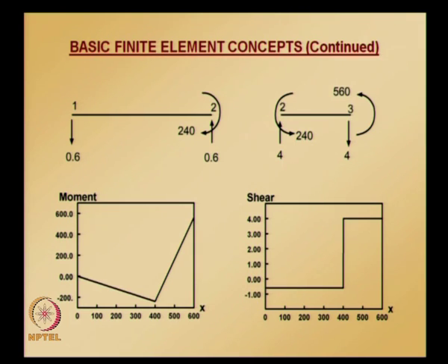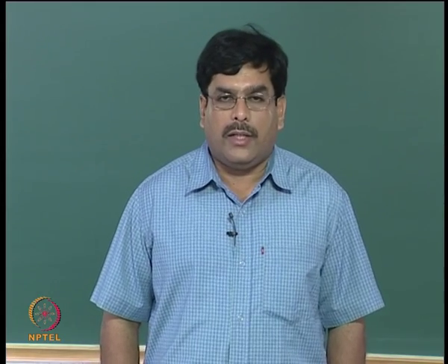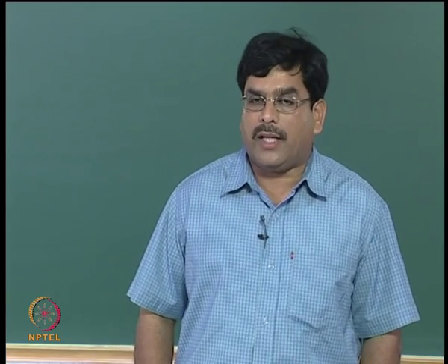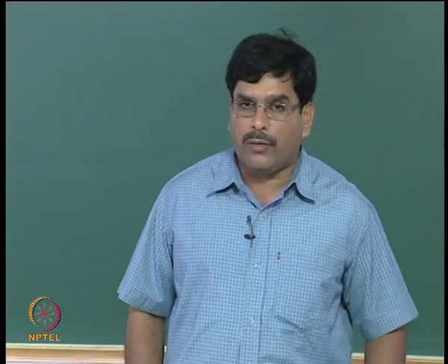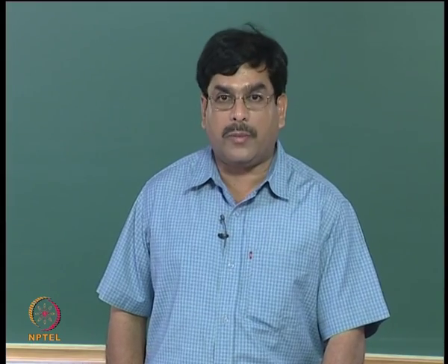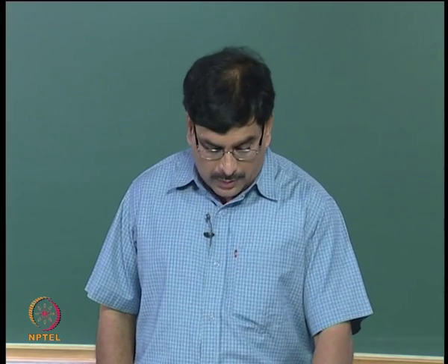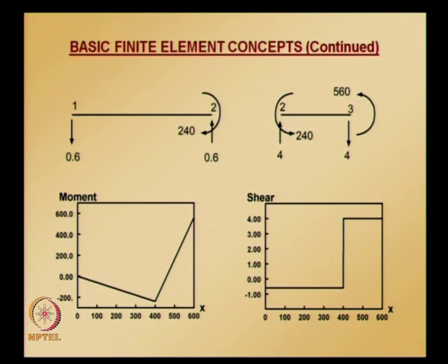Whereas if you apply those element equations to non-prismatic beams, that is beams in which EI is not constant, EI is varying along the element length, or to beams subjected to distributed loads, it may not be accurate and there will be some error in the solution.